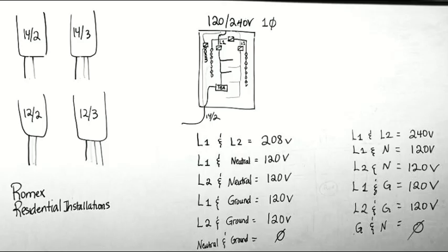So I need to make sure that these lights at least consume, for example, most of the lights that we install now consume about 0.089 amps. Now I want you guys to take 15 and divide it by 0.089 and tell me how many lights I can put on a 15 amp circuit. So you're gonna take 15 and you're gonna divide it by 0.089. Like around 16, right?